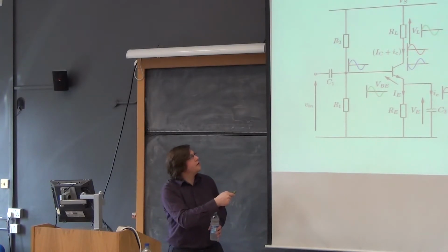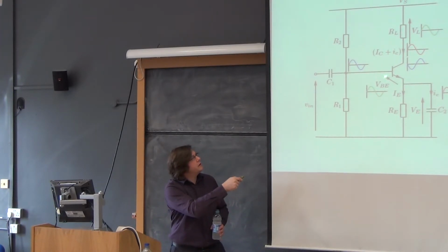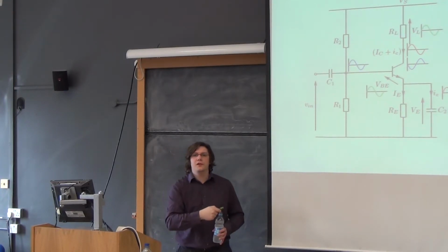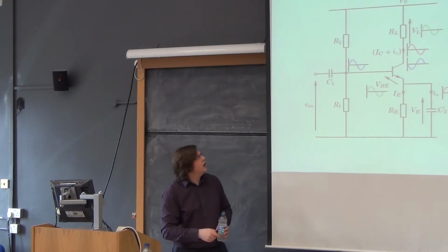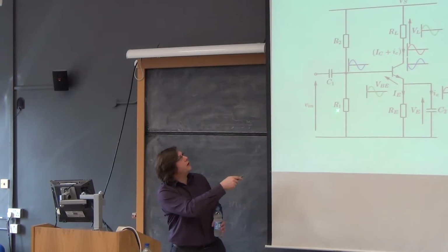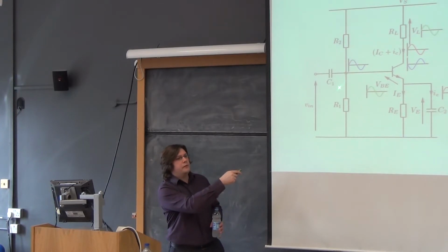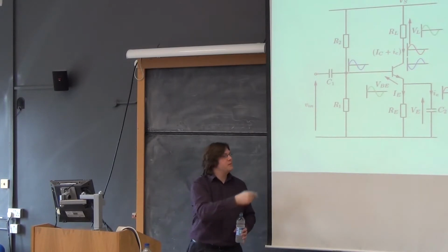Then we'd have some VBE here, which was necessary to make that 2 milliamps flow, and we'd work out what that VBE was, either with a graph or by a set of equations or whatever, and we'd produce an R2 and an R1, which gave us the right value by working out the potential divider of Vs, and then that current would flow, and we'd be happy.